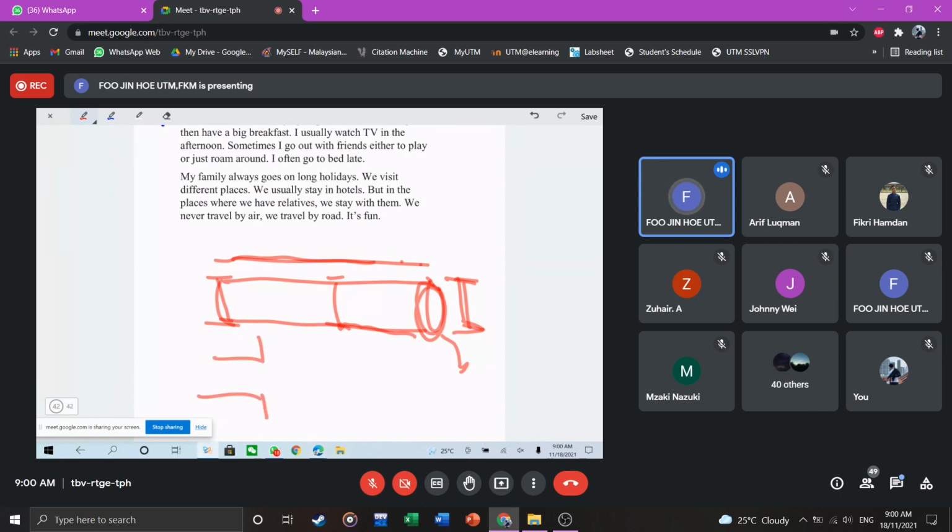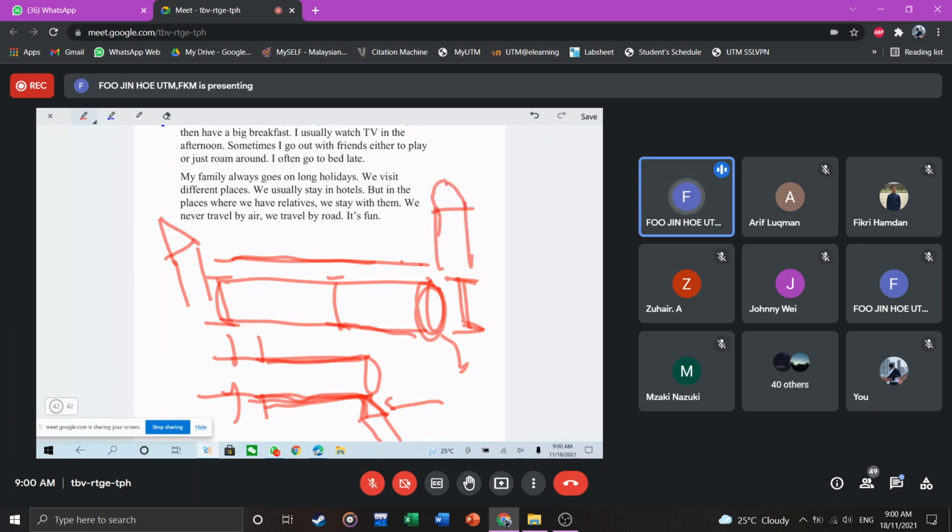So in the lathe machine, we will clamp this thing, whereby you have this cutting tool, basically to reduce the size, to smoothen it or to achieve a certain size. Ideally, you should be achieving a similar size all the way. However, we do not forget that this thing wears, especially the cutting tool. So when it wears, maybe the initial cutting tool is something like this, very sharp.